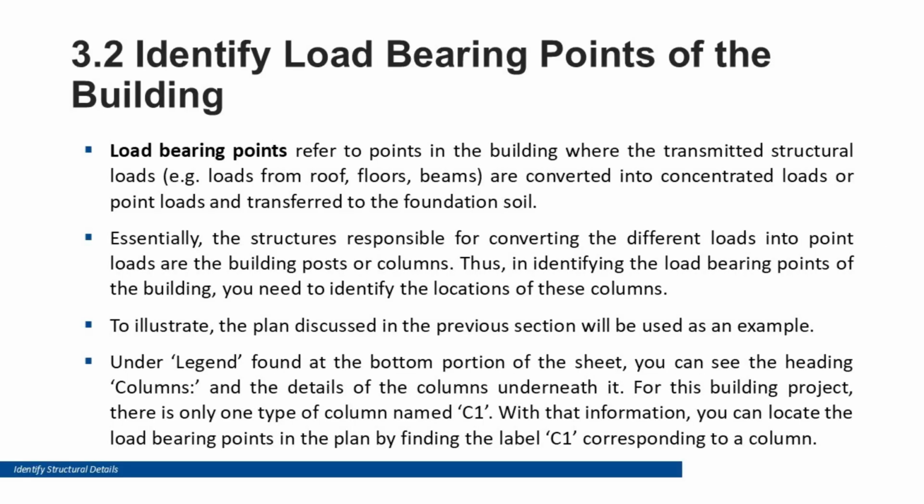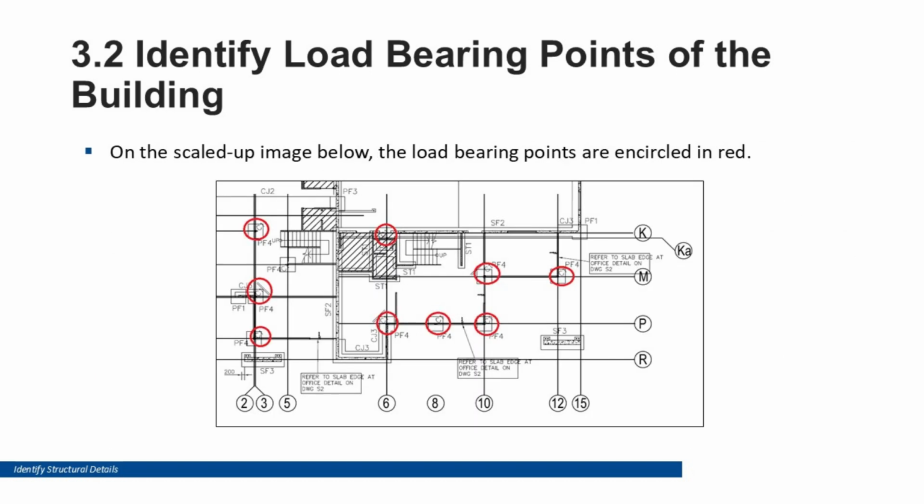Load-bearing points. Load-bearing points refer to the locations where the building's weight is concentrated and transferred to the foundation. These points occur at columns, major beams, structural walls, or junctions. On structural drawings, they may appear as column markers such as C1. Once identified, ensure these align with footing placements.